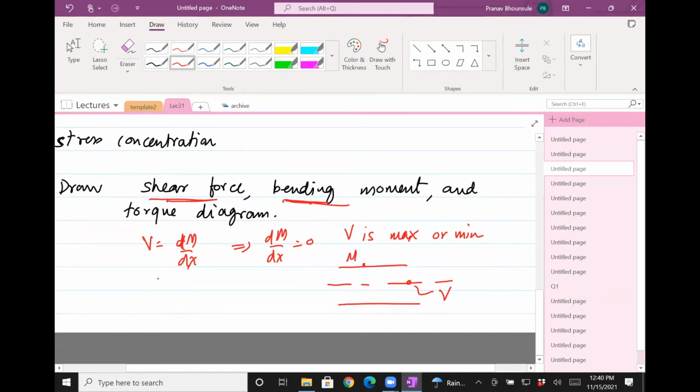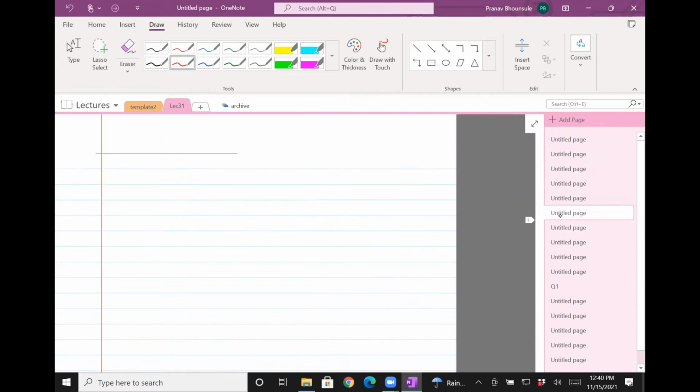Second is the fact that these loads appear at different places. Those are the reasons why you need to go beyond just drawing one diagram; you need to draw both of them. And then, if there's torque, you want to include torque, because the torque will give you a shear stress, which will also show up here. Next. Yeah, helpful? Yeah.